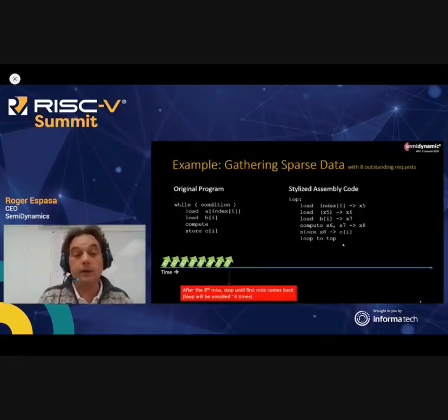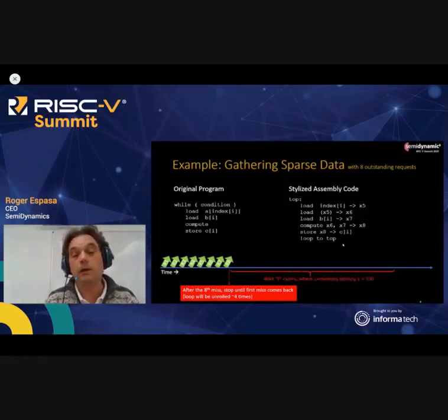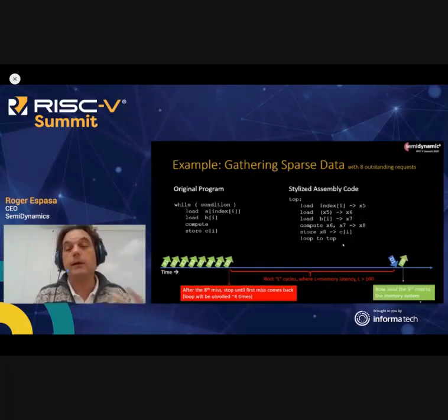Now, after the 8th request, most architectures will just stop. And they'll wait for what? Well, they'll wait for the first piece of data to come back from the memory system, which is far away. So there's going to be a long wait time, L cycles, where L is your memory latency, and typically that's over 100. Then data will come back, and at that point some resource on your microarchitecture, typically an MSHR, is going to be free, and that will allow you to make your 9th request and resume your program execution. Obviously, the long gap in the center of this picture is undesirable.